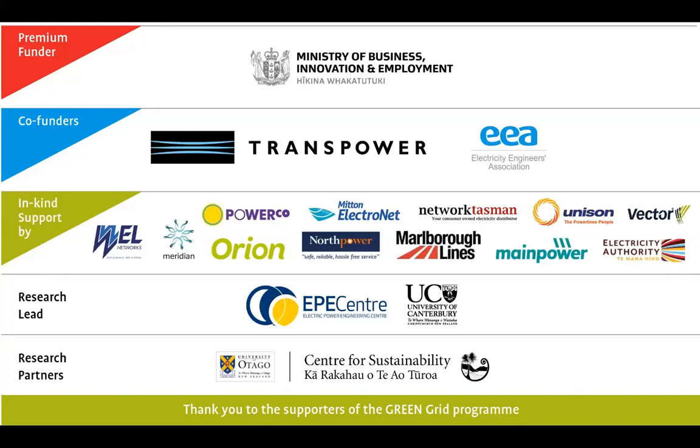Just another thing to add about the PV and EV combination is that often when you've got both, they're not acting against each other, because normally when your PV is high, as in the summer and at midday, that's typically not a time when you're charging, which is in some ways why they don't offset each other. So in some ways it's almost valid to consider them separately, because you're really concerned about EV charging when you've got your high load times, which are typically in winter at the evening peak.